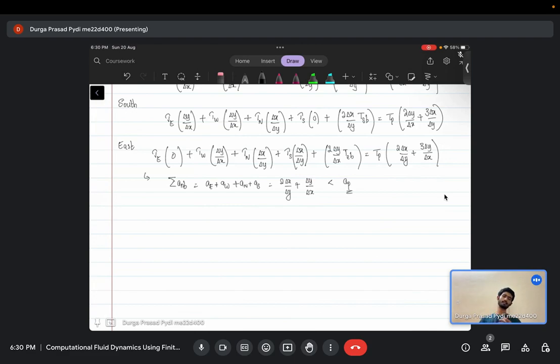So the convergence is assured. We have just derived this for a 1D case, but it applies well even for 2D and 3D problems. So for a Dirichlet boundary condition, you will necessarily have assured convergence. Now that we have the equations and the boundary conditions, we can solve this using either an iterative method or any of the direct methods.